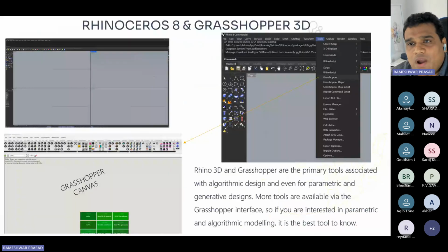Okay, so what does the UI look like? On the top left, you will see how Rhino 8 typically looks. You have 4 windows: perspective, top, front, and right. If you want, you can put in the left view as well. It is more or less like modeling software, so not much guesswork, at least for structural engineers. The 3 types of elements that I use are 1D, that is line elements, 2D, that is plate elements, and 3D, that means volumetric solid elements. The 2D and 3D are called breps, boundary representations in Rhino language.